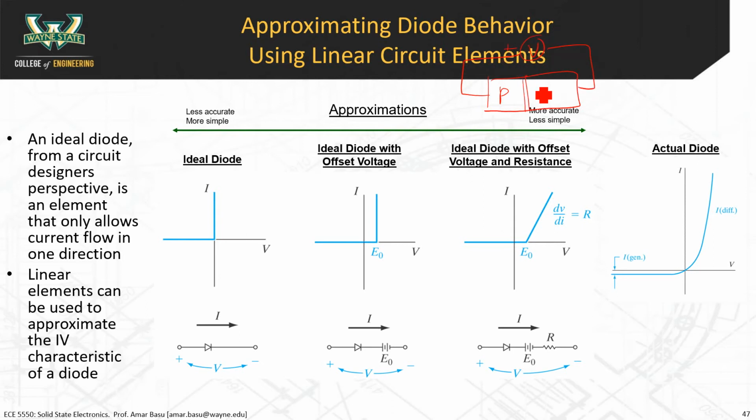The depletion region forms, and that depletion region has this voltage drop across there. But then the current is flowing through the entire device like this. So this N region is going to have some kind of resistance associated with it. This will also have a resistance associated with it. And this will be that voltage drop.